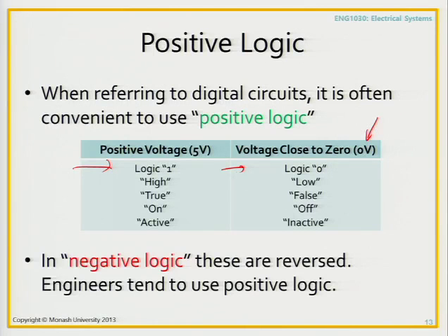There are schemes and systems where you can use negative logic, where this is reversed. So if I talk about a 1, I'm actually talking about a 0 volt, and everything is switched between positive and negative. Pretty obvious once you understand what positive logic is, but important to define because, by Murphy's law, if someone had done something in positive logic and you didn't tell the other side, someone is going to interpret everything as negative logic because that's how they work, and then disaster.